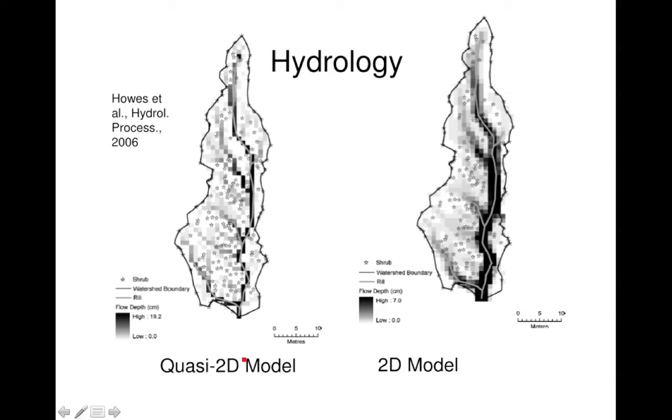So when they applied a rainfall to the system and then routed the flows through the landscape, the dark lines here are where the highest flows were. Okay, and you can see the highest flows are really concentrated around the stream network. It's given by the topography. And the problem with that is that the flows can actually be larger than the capacity of that local channel. So in reality, the water flow should be spilling out sideways. And a two-dimensional model can sort of handle that a little bit better. Not necessarily always, but sometimes.